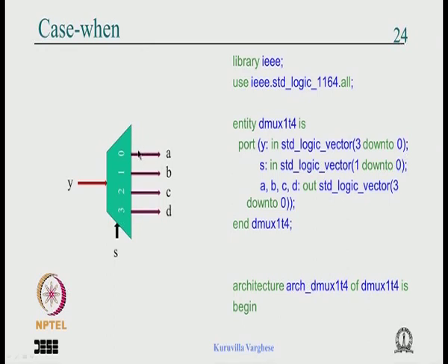It is connected with a high resistance to VDD, high resistance to ground, so it is not a strong drive, so the input is kind of floating, and the various inputs driven by this output can, depending on some noise pickup, start switching. Okay. So don't tri-state it unless it is a bus,